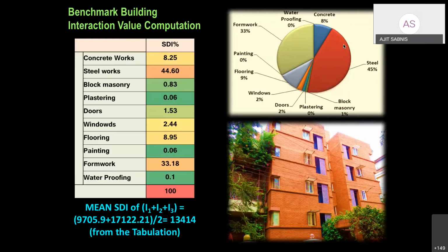When you start looking at it holistically and then at a much larger picture, taking several eco parameters into consideration, steel has the maximum impact and concrete has comparatively less impact. This is mainly because we are now looking at multi-storied buildings, the frame structures where RCC is predominantly used. And when you look at it only from the embodied energy and embodied carbon point of view, yes, concrete has the maximum impact for the simple reason that cement is involved in it as a part of it.